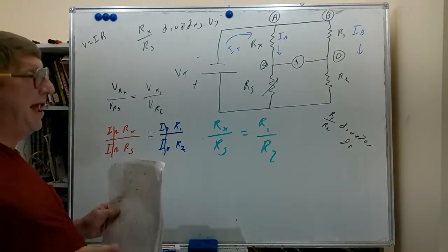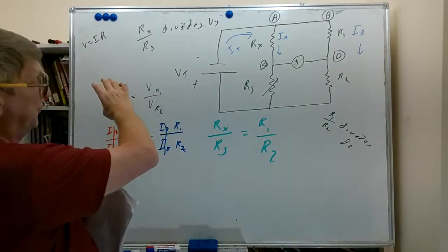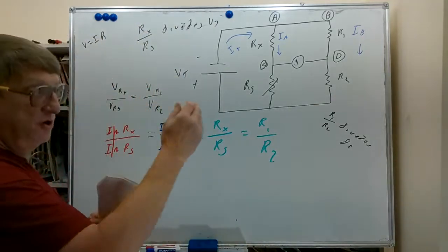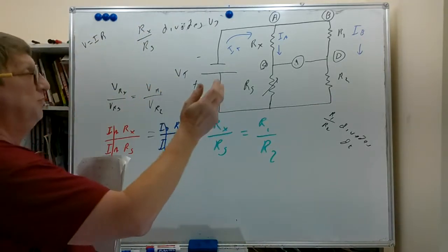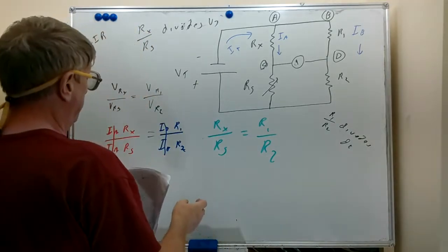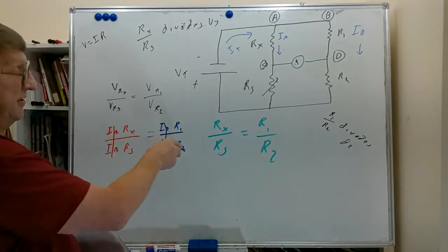So when the bridge is balanced, when we have zero, when the voltages are equal, which we looked at, the voltage ratios being equal, which gives us the same voltage on C and D, we have no current through the meter, no potential difference, no voltage read by the meter. We did a substitution for voltages. Now we've canceled out the currents.